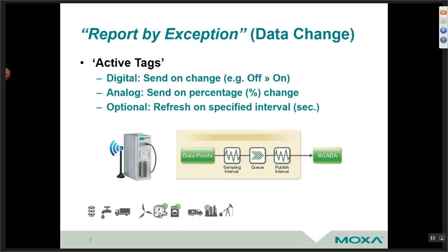Another fundamental technology, and some of you may already be aware of this, particularly those involved in factory floor applications. Some of the foundation technologies introduced with CAN-based networking and DeviceNet type technology from years back know about some of this, where the concept is you don't just poll even though there's no change in data, but rather send data as it changes.